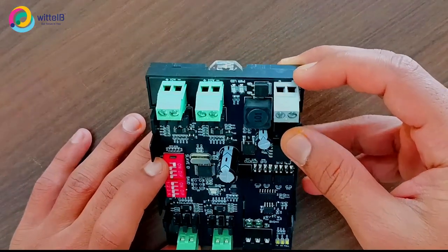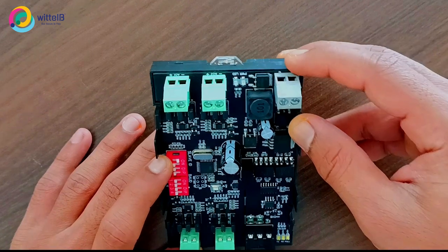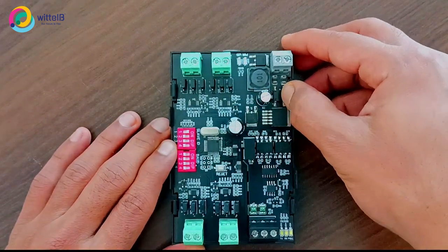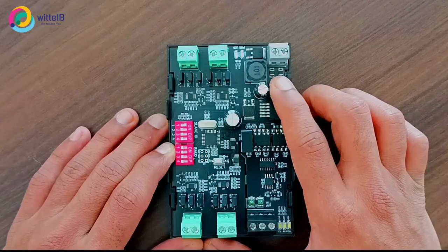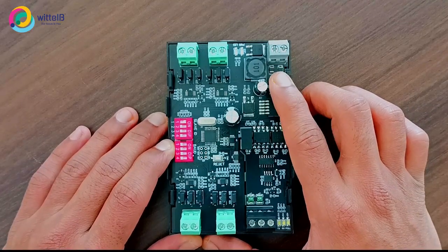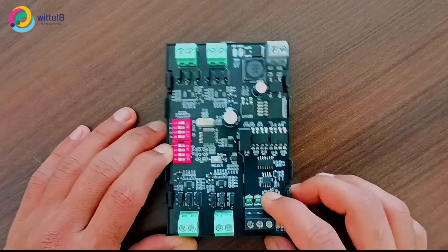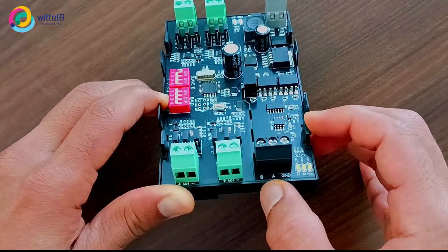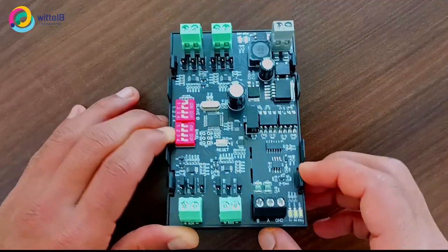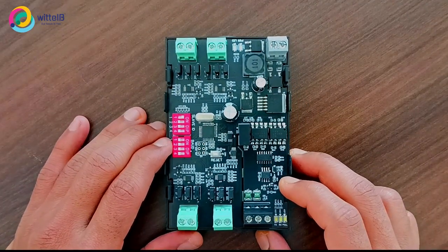For this power supply we have provided positive and negative terminals, where we can connect up to 24 volt DC in any direction. Here we use a bridge rectifier which supports reverse connection for the board. And here we have the RS485 for communication. In this RS485 the configuration is B for negative, A for positive. So we can connect the RS485 cable with the PC to get the data.